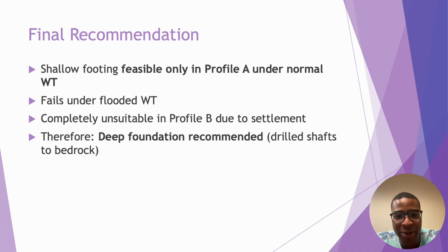So closing out with our recommendations and observations, the shallow footing was feasible only in profile A under the normal water table. It failed under the flooded water table conditions, and the design is completely unsuitable in profile B due to settlement. So the deep foundation is of course recommended here to err on the side of safety. The drilled shafts would be sufficient.